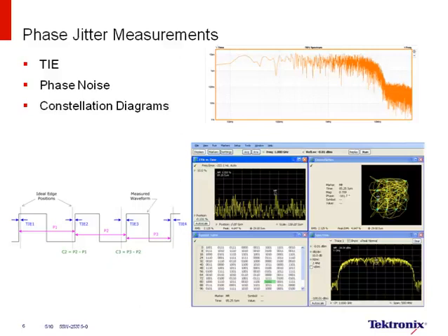So the short answer to the first question is that if you get all the parameters right, the loop bandwidth, the equalization, the PLL order, the maximum spec, if you do all that, then you have a very high likelihood of calculating the receiver BER from making a transmitter BER measurement.